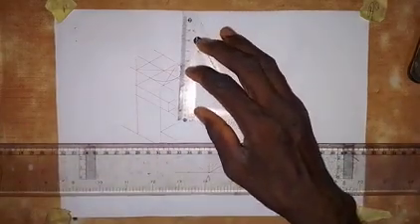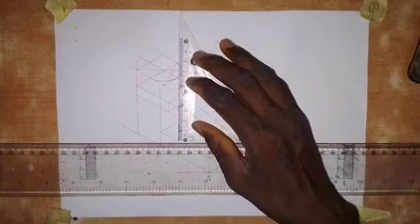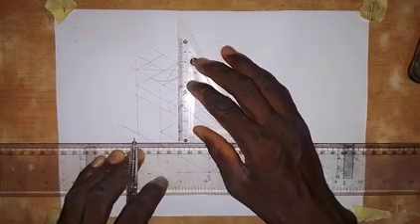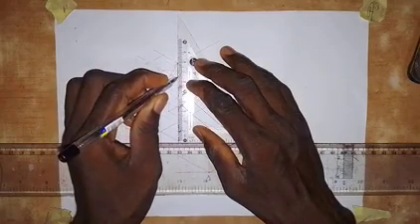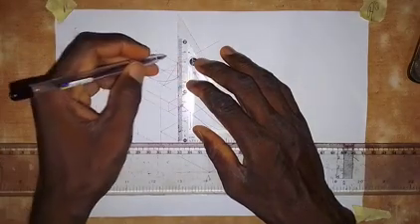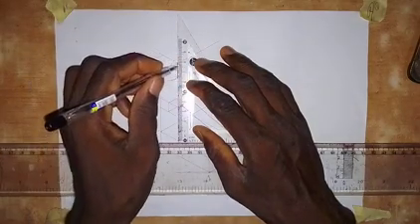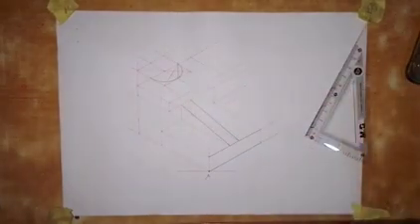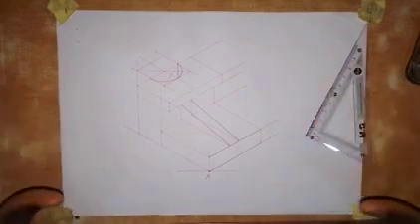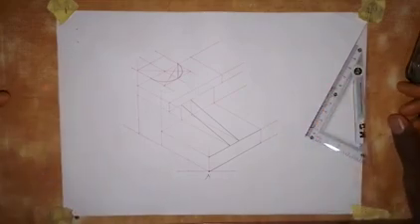The next thing that we are going to do to show that this is a semicircular hole is to come to this point and draw this line as a thick line. So this line goes down. That is what makes it a semicircular hole. The next thing that we are going to do is to thicken the outlines, which I'm going to do while I pause the video.